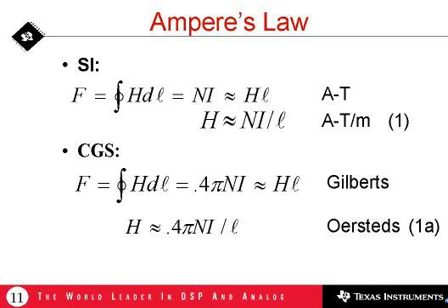The field intensity would be constant. It would equal 10 amperes divided by the circumference of that circle. But if the path were irregular and not centered on that current flow, then I would be hard put to calculate the field intensity along that path. But I know clearly that the total force around that path is equal to the enclosed current.